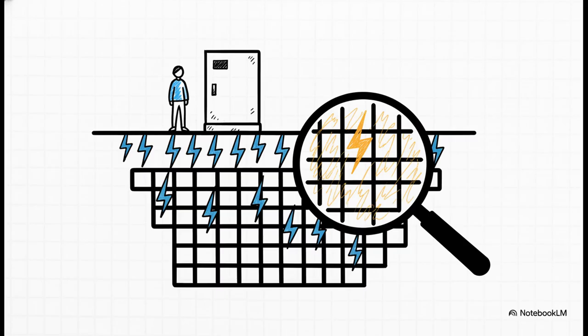ground? Well, applying this decrement factor directly dictates the maximum grid current sizing. For faults lasting under a second, which is exactly where that DC offset is strongest, this calculation ensures the physical copper grounding grid buried beneath the substation can rapidly and safely dissipate the fault. If you size those conductors too small, they might melt, or far worse, they could generate lethal step and touch voltages right on the ground surface where personnel are walking around.